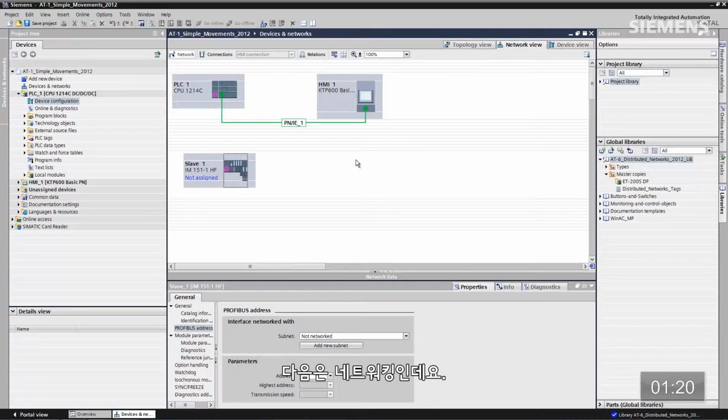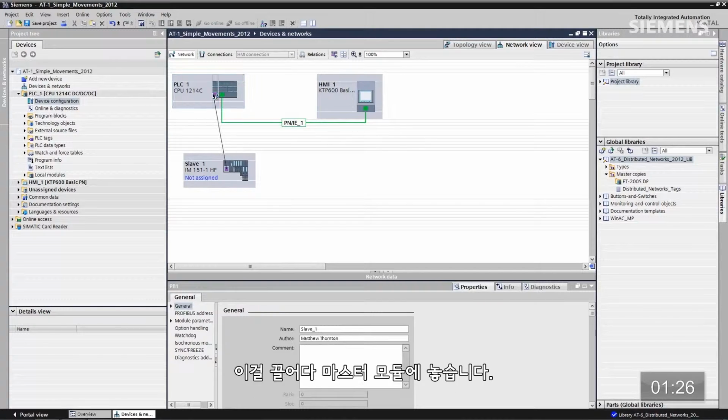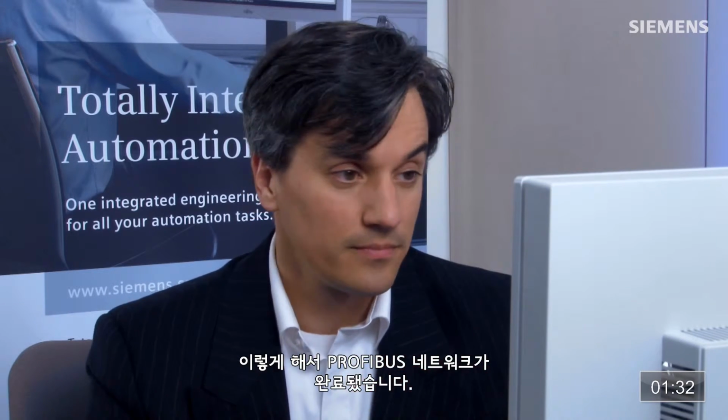The next logical step is networking. So let's mouse over the Profibus interface of this rack. Let's drag it to the master module. When I let go of it, it'll auto-create the logical physical connections. The Profibus network is done.